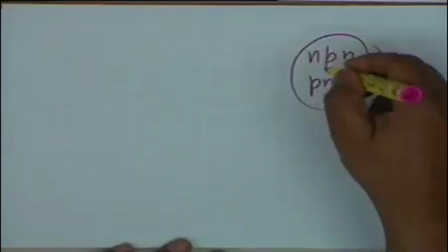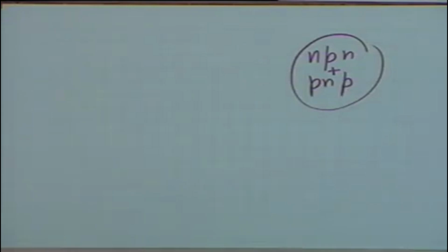In semiconductor devices we can have NPN and PNP transistors. By making a combination of two such transistors, instead of using two NPN or two PNP in a class B push pull amplifier, if you make a combination of NPN and PNP, then you can avoid the transformer. Let me draw this circuit first, then I will explain.